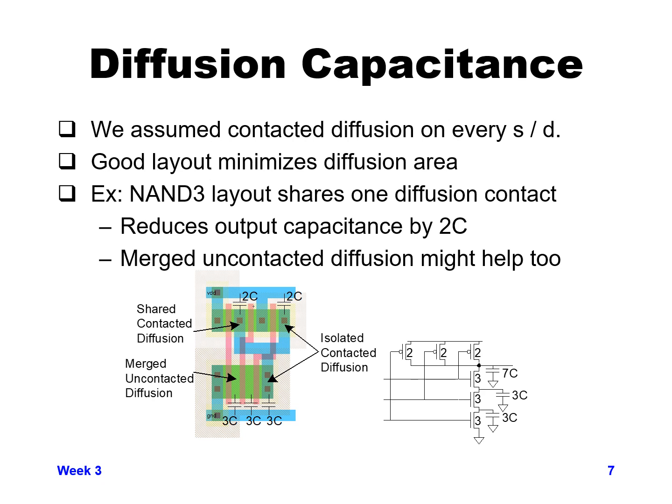In reality, it would probably be even slightly less than that, because since you don't need a contact between those two gates, the area of that source drain area is slightly smaller than even a single contacted source drain area would be. So that 3C value would probably be even less than 3C by a slight amount, maybe 2.5C or something. So that can reduce your overall capacitance that you need to drive, both for pulling up and for pulling down.